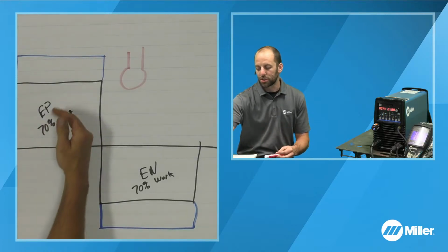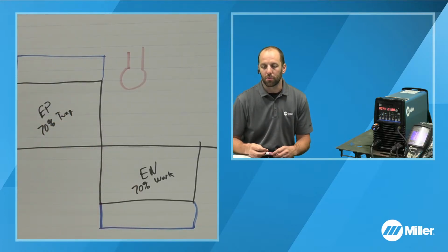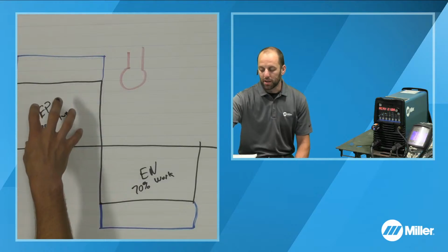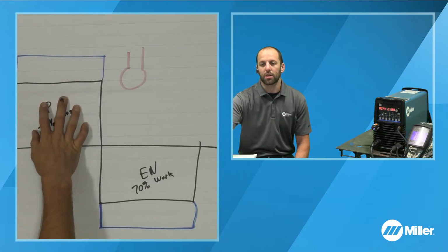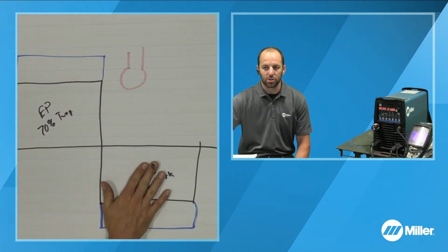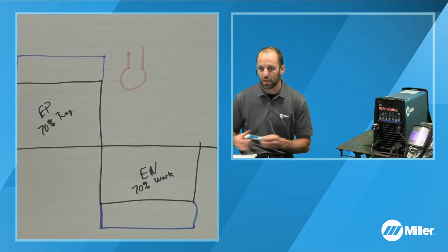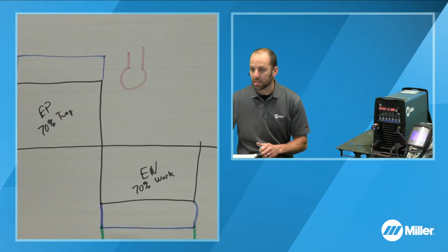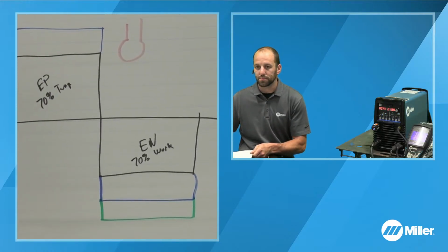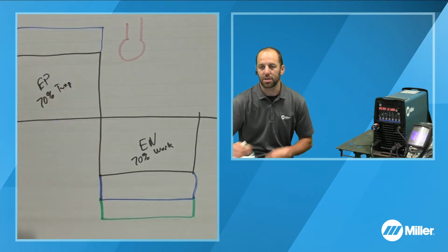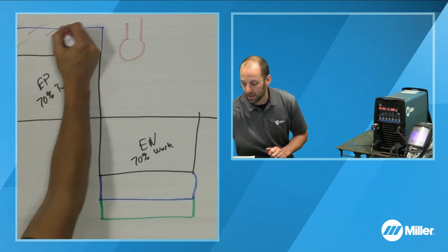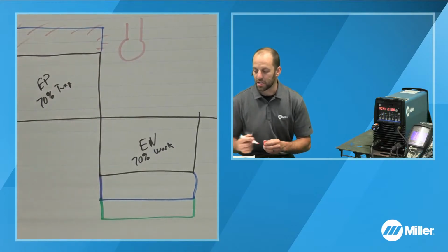But we don't want to skew too far from each other, and I'll talk about some of the ratios. We want to make sure that we get adequate cleaning, but we can also start adding extra heat. So if we pump extra heat down into our work without adding extra heat up onto the tungsten, maybe we say, you know what, we're not going to add that extra heat up onto the tungsten.